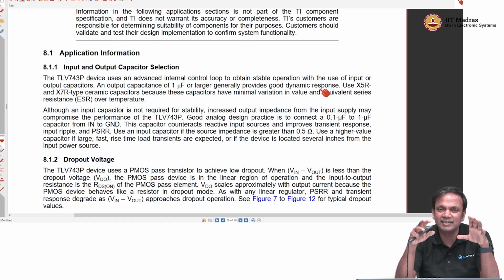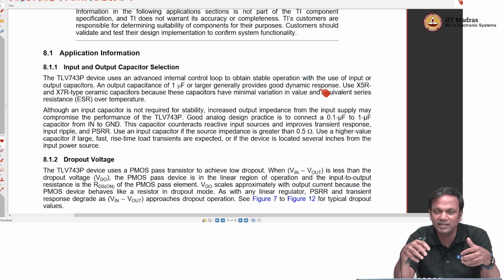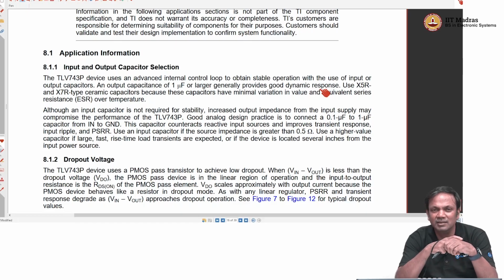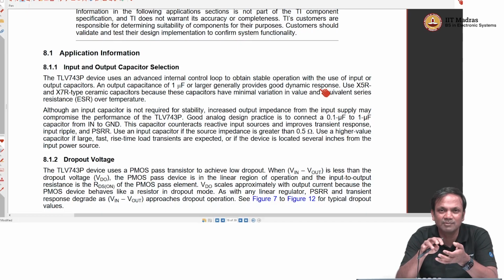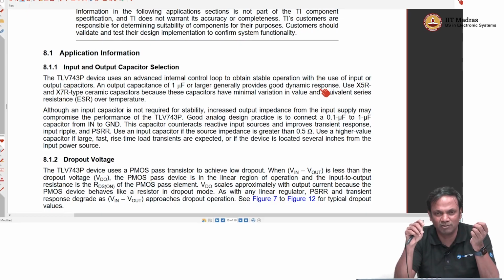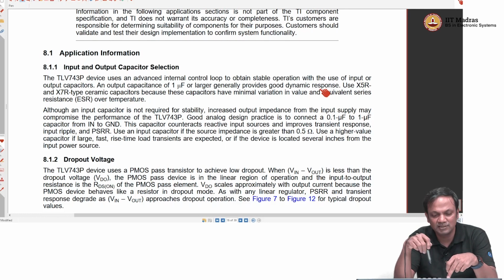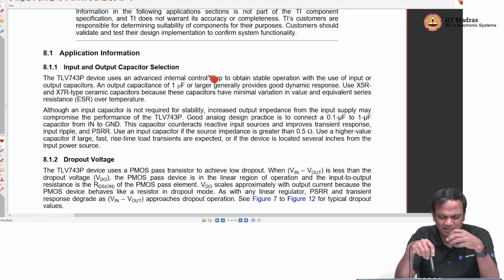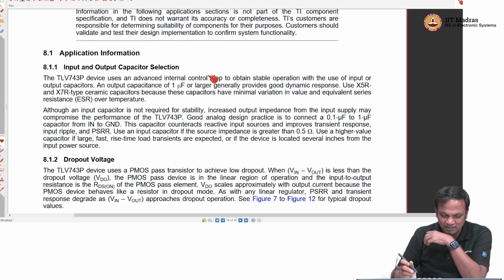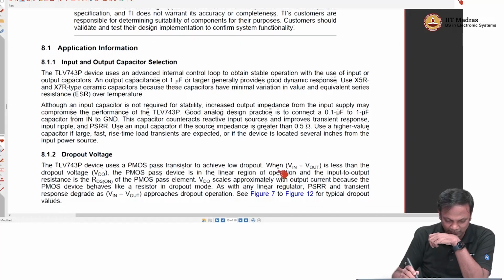So, for any regulator, for any feedback circuit, for any chip that you use that has an analog feedback system, it is important to understand, okay, now I am loading that feedback system with something, will the stability be compromised, what is the acceptable level of load. So, in that context, it is good to know what the output capacitance is. They have said 1 microfarad, so we will stick with 1 microfarad, right.